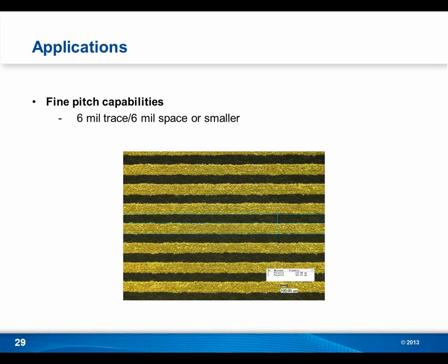So again, the MIDs and the laser structured MIDs basically add a circuitry to a plastic part. So we use all the sides of the plastic part, and as we see in some of the applications, we can also create through holes to have an electric current basically travel through the part and on the other side and continue on there. But it's really not a process that's designed for multi-layer or replacing a multi-layer circuit board in this case.